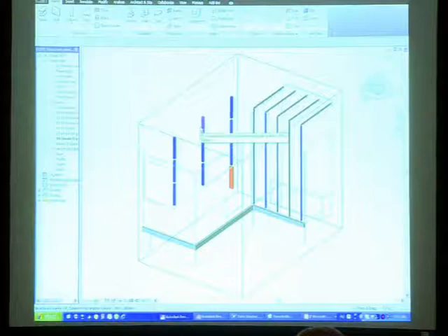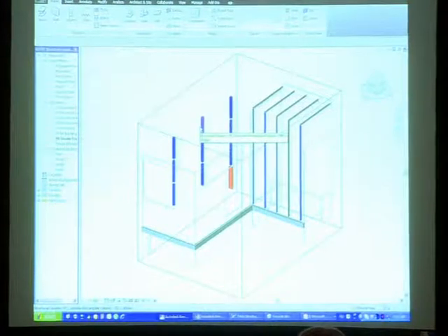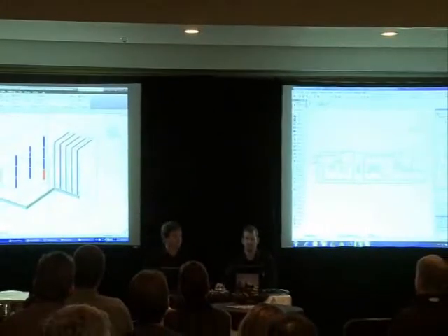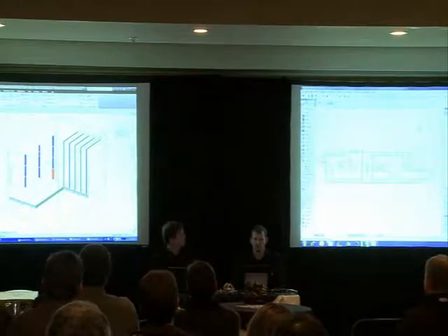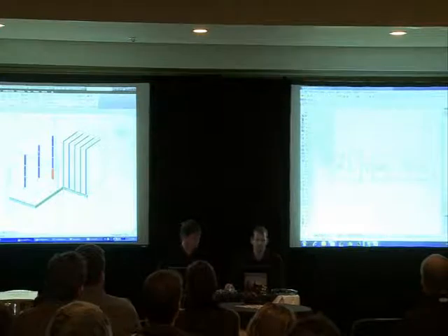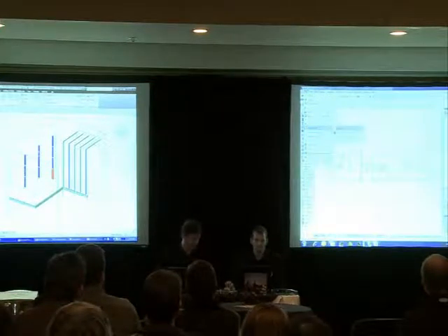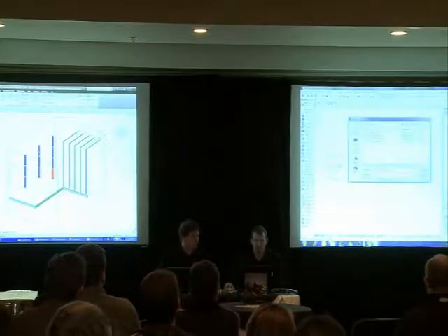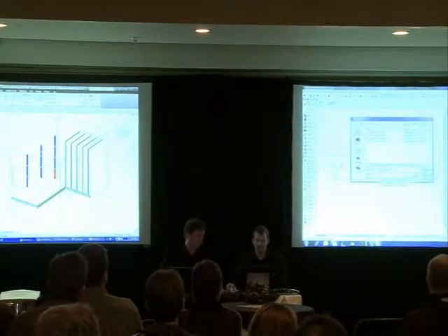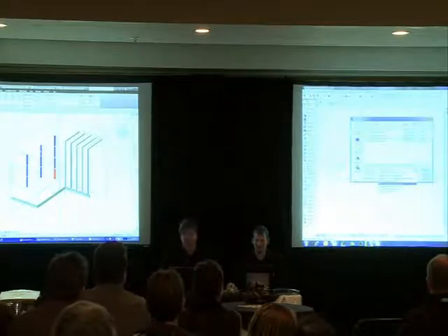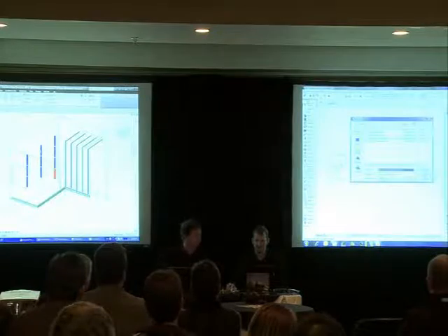So now, what we will do, I have exported these as an IFC file for ArchiCAD, and we will open this, we will merge this into ArchiCAD. So we will go to the structural floor plan, as you will see it there. And there, we will merge these into ArchiCAD, but in an intelligent way. What we will do now is merge, and ask for the appropriate translator. Of course, we select the file. And then, not the general, but the Revit Structure translators. As you see, the translators work both ways, back and forth.